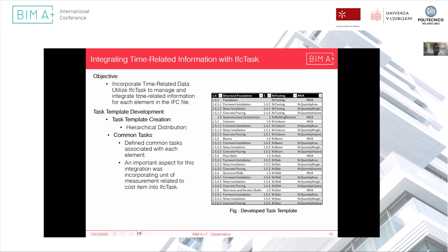The next task was to integrate the time related information with IFC task. So for this, we created a task template to incorporate time related data. We utilize IFC tasks to manage and integrate the time related information for each element in the IFC file. The task template was developed in a hierarchical distribution, and the common tasks were identified for each element. For example, a slab will have three tasks, which is rebarring, concreting, and the formwork installation.